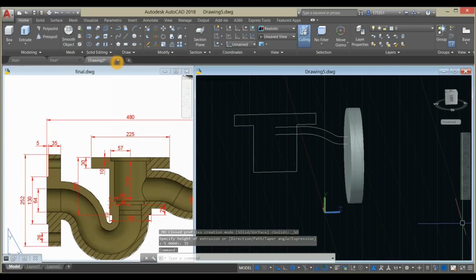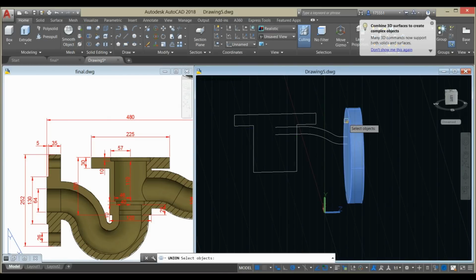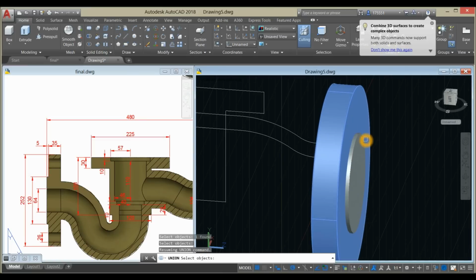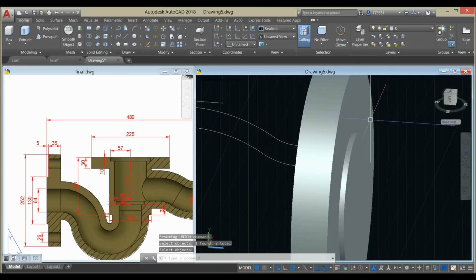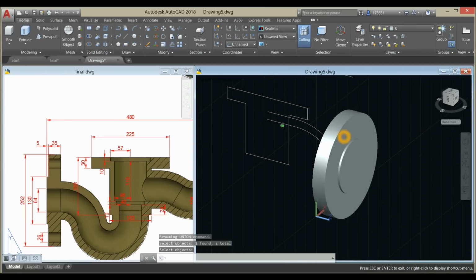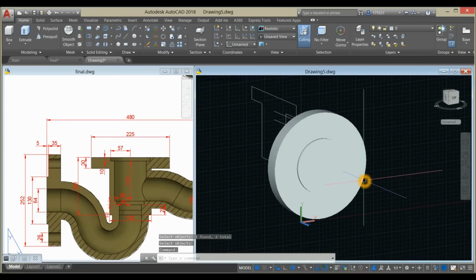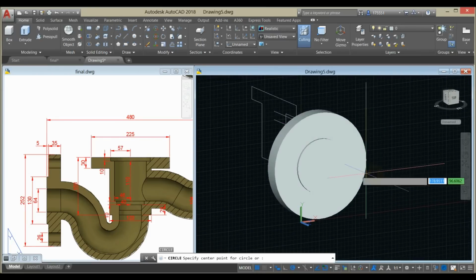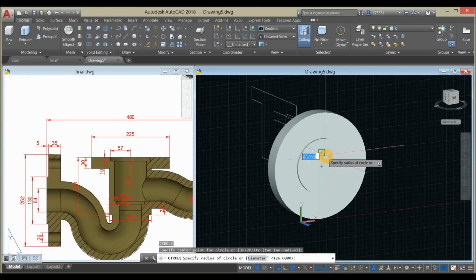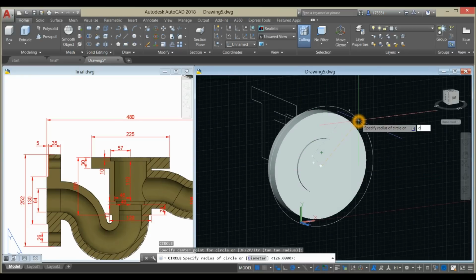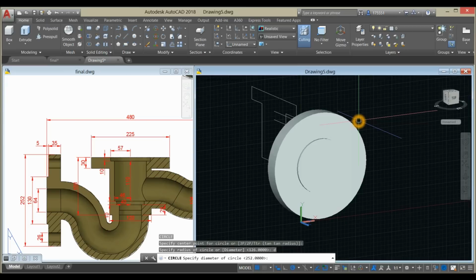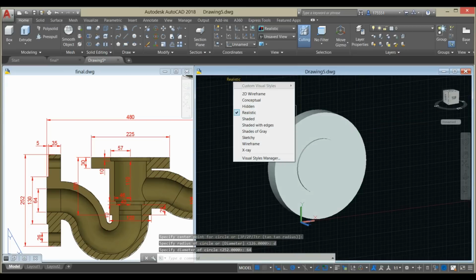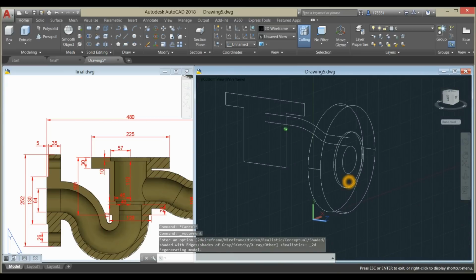So what I'm gonna do is combine or union the objects. So this one and this face, this is raised face, so click that, and I'm gonna poke a hole through here. So seek for circle again, click that midpoint or center rather, type D for diameter option and enter 64. I'm just gonna check doing 2D.